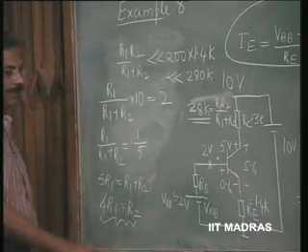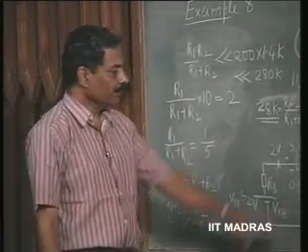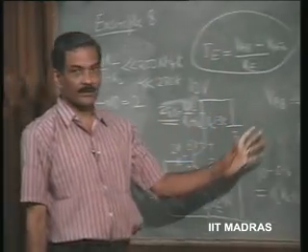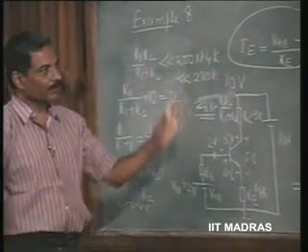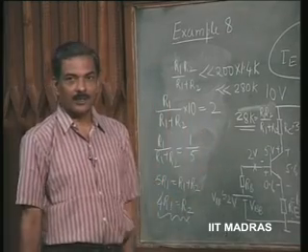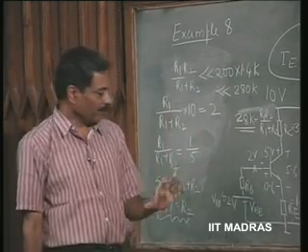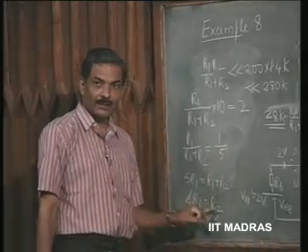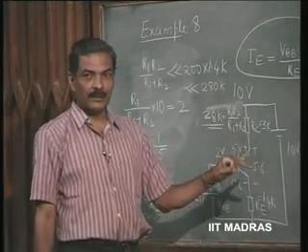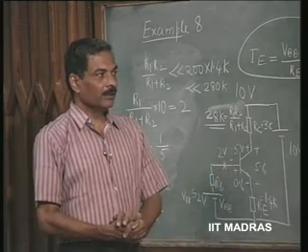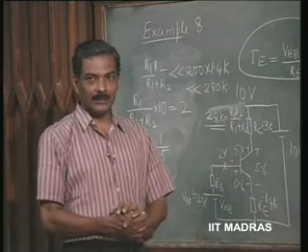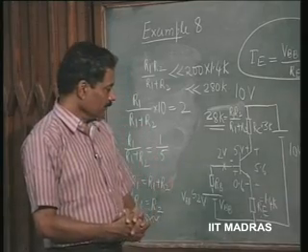So, that will fully satisfy this biasing arrangement, and therefore, you can again redraw the structure with R1, R2, VCC, RC and RE. That is the complete structure. So, I would like you to evaluate R1 and R2 and redraw the biasing circuit. In the next class, we will give you the complete circuit. Please try to attempt this in your hostel.